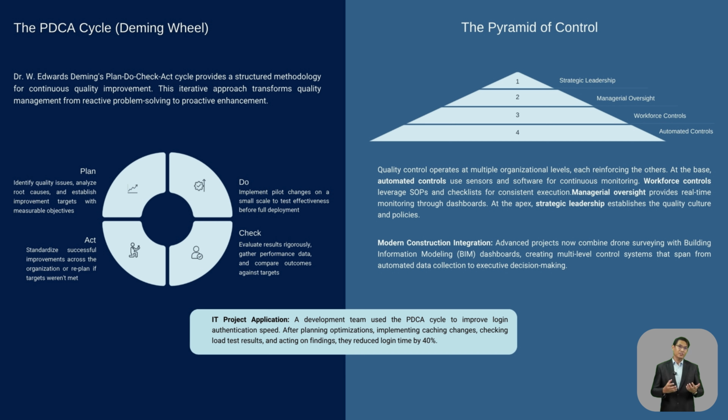So in construction, this cycle could be used to improve site cleanliness, which affects safety and workflow. A plan is drawn, bins are relocated for convenience. Outcomes are observed over 2 weeks, that is Check, and adjustments are made, that is Act. Now, the PDCA cycle ensures that lessons learned lead to operational improvement.